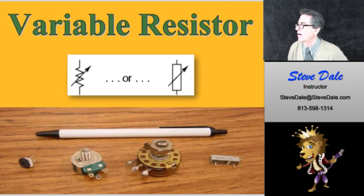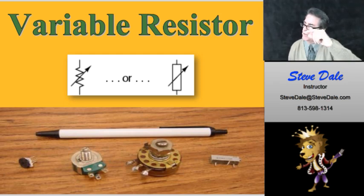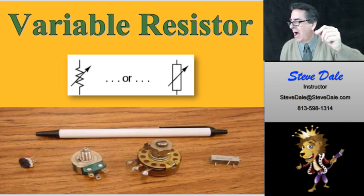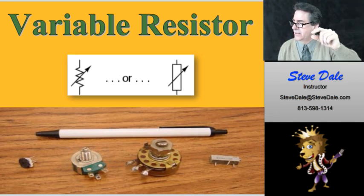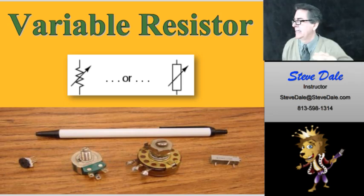Okay, these are variable resistors. Now, what I've seen on the exam before is, see the resistor on the left side there showing the resistor, and then it shows like an arrow through it. That arrow through there means variable. Okay, that means that you can actually turn it or adjust it. You can turn those ones down. Those are also called potentiometers or rheostats. You may have heard those before. But you can turn a knob or a dial, or even with those are like set screws there, and you can turn it and make the resistance more or make the resistance less. Okay, and the variable part of that is the arrow.